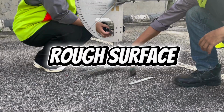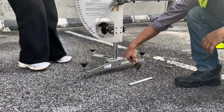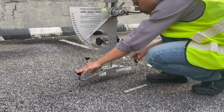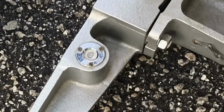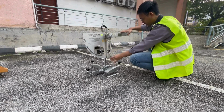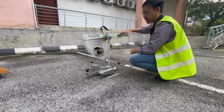The testing began with the rough surface. Clean the area to be tested using a brush. Set the base level by means of the spirit level and 3 leveling screws on the base frame. Adjust the base until the bubble is centered in the eye. Adjust the pendulum height so it swings freely and reaches 0 on the scale. If it does not, record it as an apparatus error.